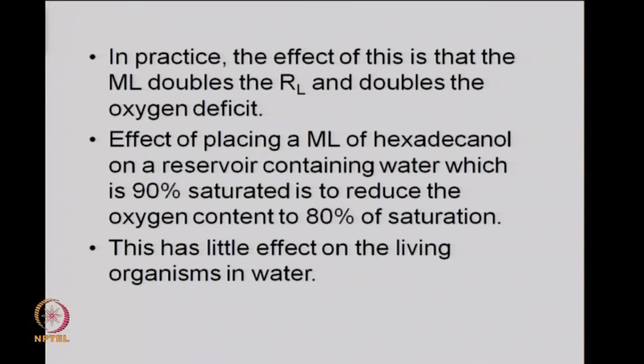But the encouraging part is effect of placing a monolayer of hexadecanol on a reservoir of water would reduce the dissolved oxygen content from 90% saturation to about 80% saturation. That does not have much effect on the living organisms in water, thereby making this C16 alcohol, hexadecanol, one of the most promising agents for retarding evaporation.